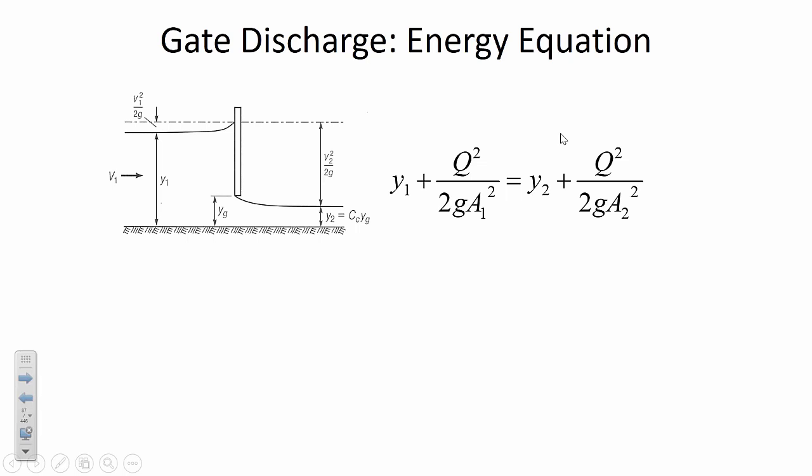And I've mentioned before that when you put an obstruction into a channel, the water will pool upstream of that obstruction until there's enough energy that it achieves equilibrium again. And it's that unsteady condition that's the most interesting. I hope we get down into the lab so that we can observe, like when you first turn on the bench and the water level is starting to rise upstream of the gate, it's not quite in equilibrium yet.